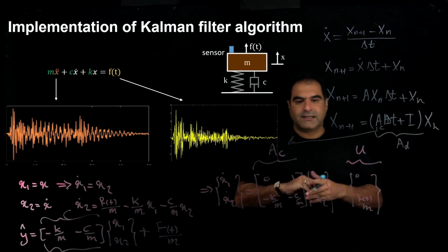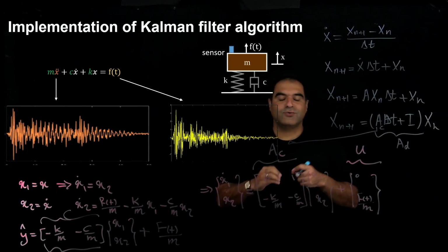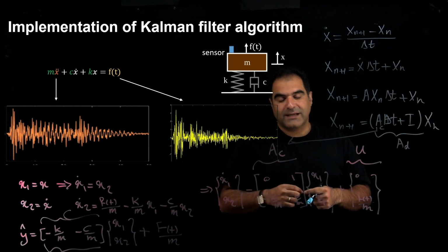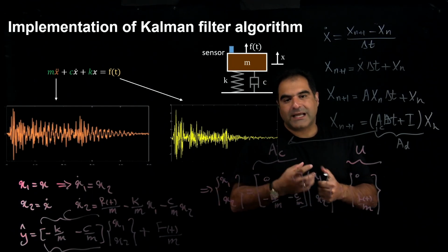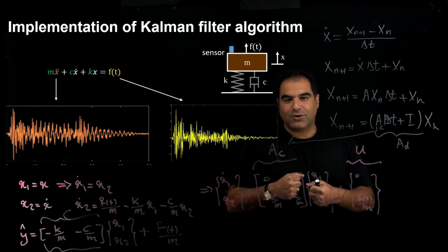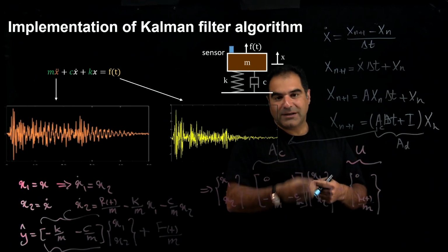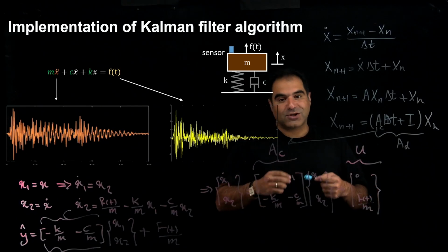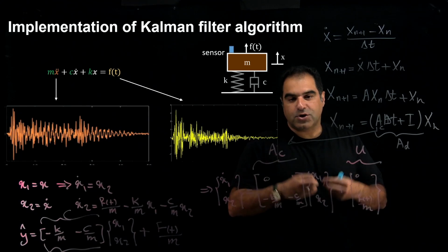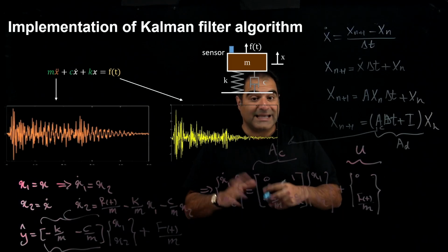But you need to keep in mind that the Euler scheme, or Euler time integrator, is not an appropriate choice for a dynamical system, for a vibrating system, because it cannot hold the energy of the damping term. I'm going to show you in future presentations why the Euler scheme is not a right choice for a dynamical or vibrating system, and it's better to go with other choices like Runge-Kutta or Houbolt's method. These are the good options, which we will talk about in the next slides.